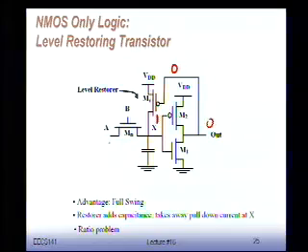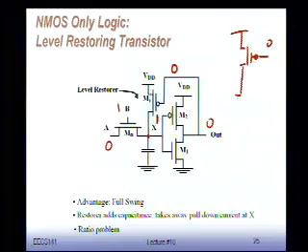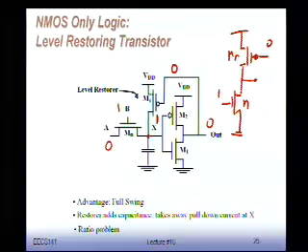Now we're going to try to put a 0 here, so this is 1. We try to pull this node low. We put a 0, we would like to make the gate switch. So again, what you see here is a device that temporarily looks something like this. This is my NMOS, this is my MR. This is equal to 1. I have an NMOS device that tries to pull down this node. But if this device is really big, it's a ratio, and this looks like what?